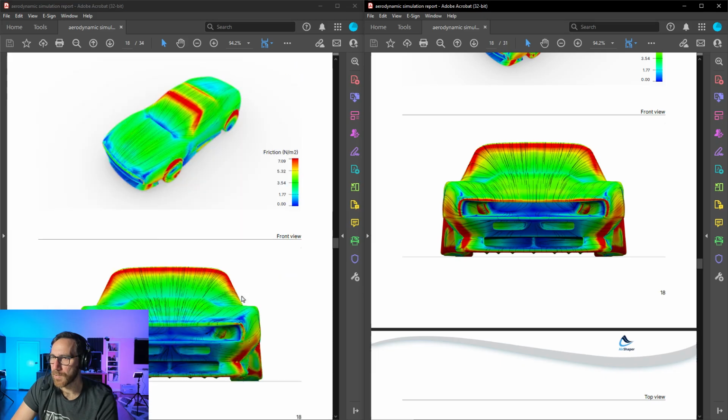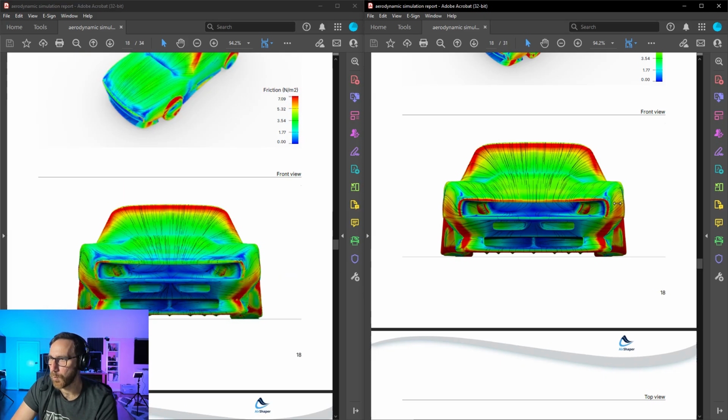And again, as we look at this thing from the front, we can see the red and yellow is creeping a bit further up the quarter on this one here. We actually have a red all the way around the front here. And again, that's likely because of the size of the geometry at the nose of the car. The low resolution probably just doesn't have a small enough cell size to be able to capture that accurately. So there might be one cell there on the low one where there might be like 4 or 5 in that same area. So it gives us more accurate representation.